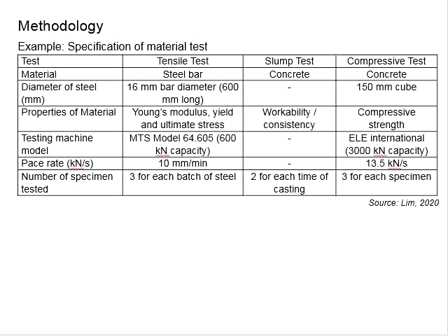In the case that you are using the Eurocode, but your cube is used to determine the compressive strength, there should be a conversion of the result acquired from the cube into the equivalent strength in the cylinder.